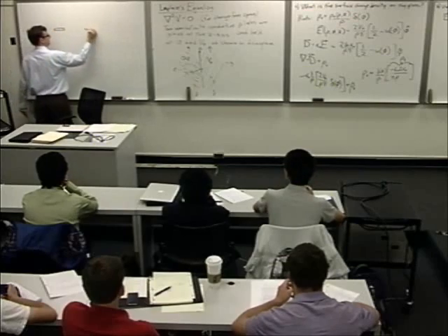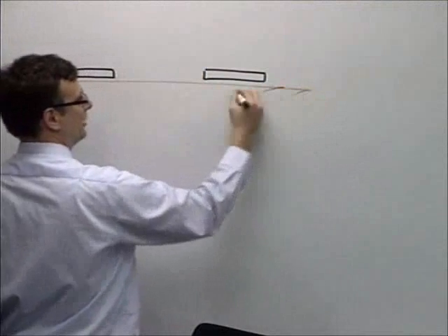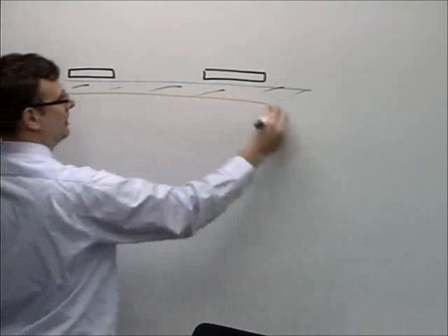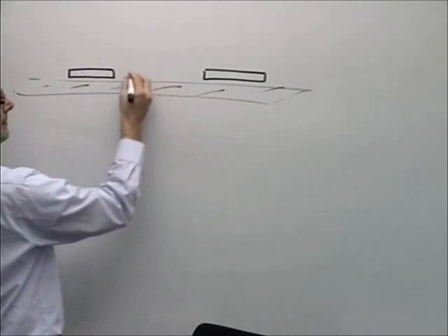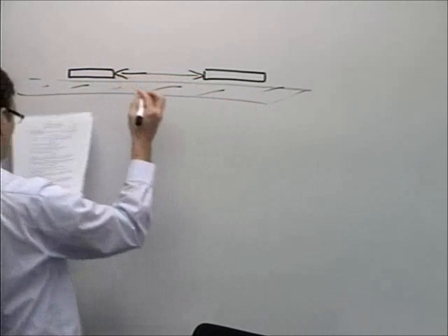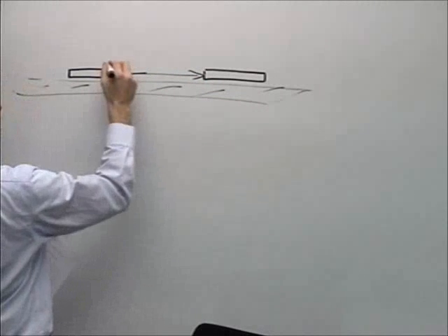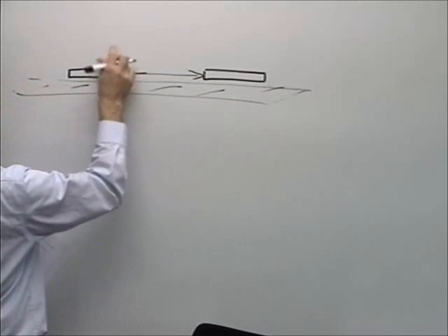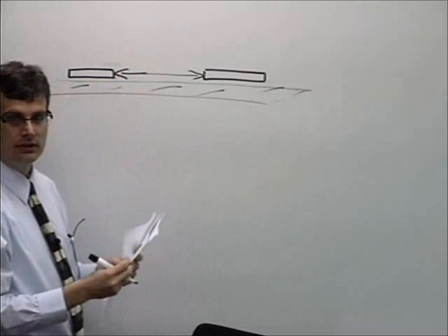So coplanar strip, you've got circuit traces, maybe like a thin dielectric that doesn't really influence the propagation very much. But you've got two plates that are side by side with relatively little intervening space. And you can actually use this result and the attendant charge densities to estimate the capacitance. Yes?